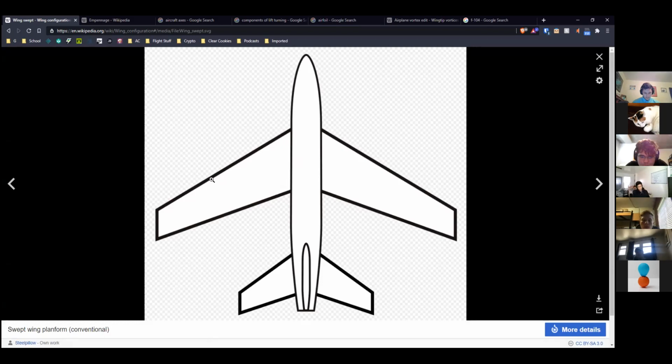parallel to the chord. So in this, I don't know if I can draw on this quickly and easily, but basically if the air is coming this way, then the part flowing across the wing this way would contribute to lift, and the part flowing across, which therefore would contribute to drag, and the part flowing across perpendicular to the chord basically doesn't have an effect on performance. So you can reduce the drag at those higher speeds for free, basically. You don't get the lift out of it, but you can shed some drag.